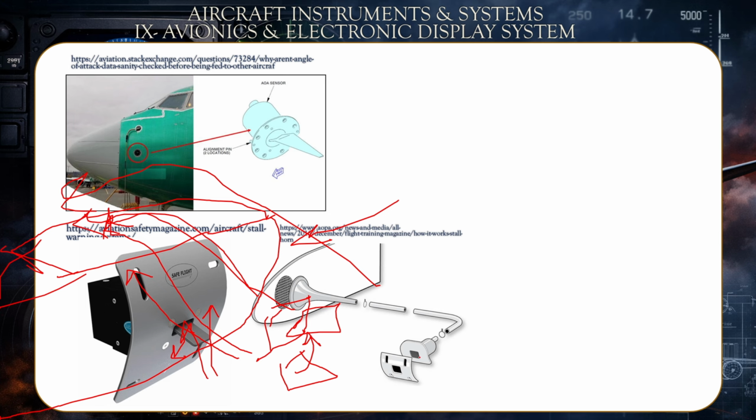Or in this case, to the right, this switch, when it goes up, will open a cavity, allowing the air to flow within a tube, and that tube would be connected at the end with a horn. And the horn would start screaming, it would start whistling, indicating a stall condition that is affecting the aircraft, and this means that the aircraft is in a precarious condition, about to lose lift and to fall from the sky completely.